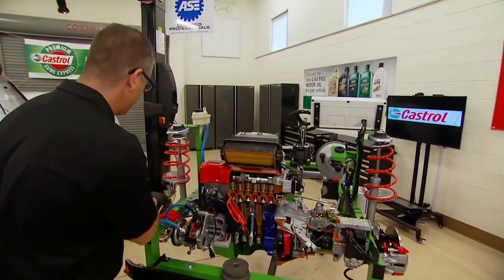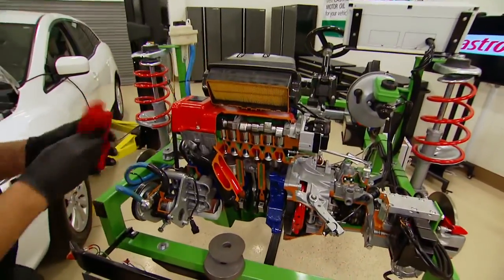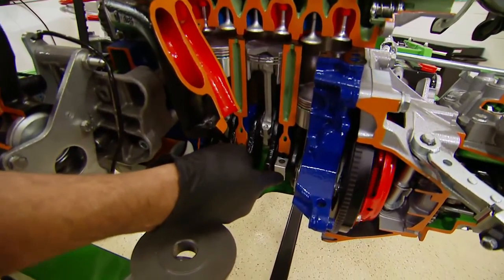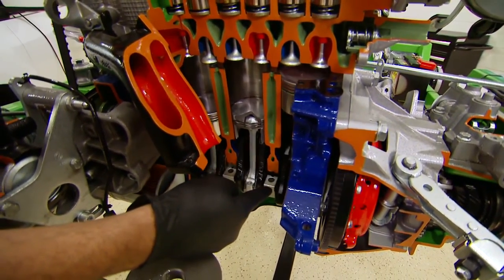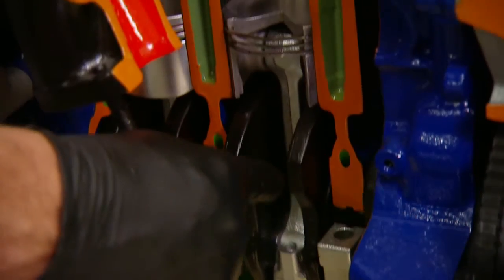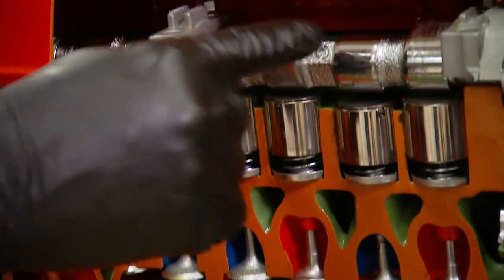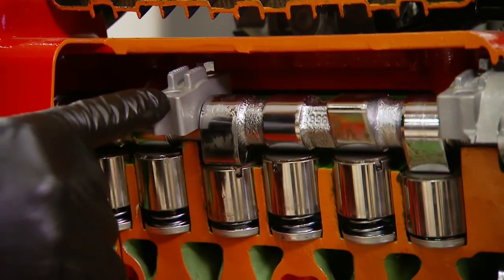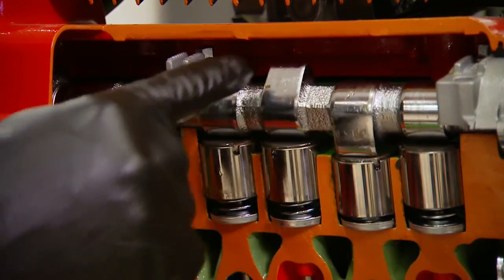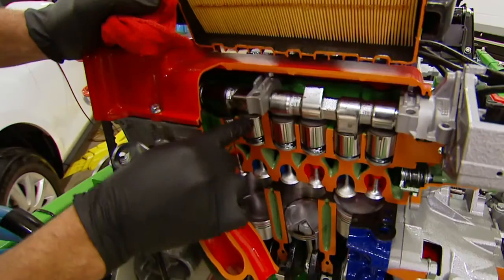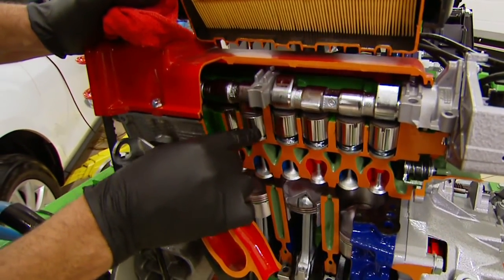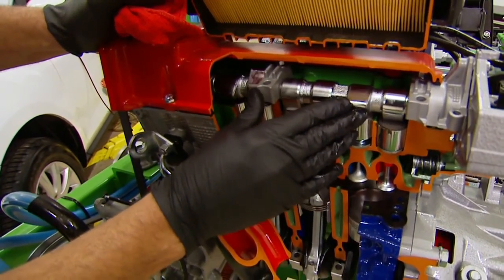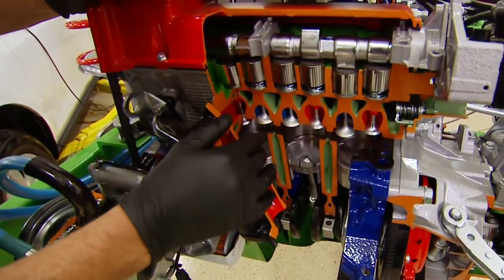Now, this overhead cam engine actually has passages that go through the whole complete engine. You can see down here where the crankshaft's running, all these connecting rods and main bearings have a thin film of oil. Now, if you move up here, you can actually see this is an overhead cam. So each one of these cam bearings actually have an oil gallery that allows the oil to come up here and lubricate each one of these cam lobes. They spin around and they go on these flat tappets or followers, which actually opens and closes the valves. Now, all the lubrication has to take place up top and below here, or this engine's going to have problems.